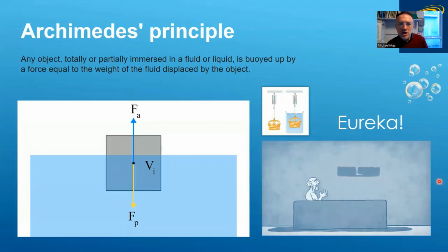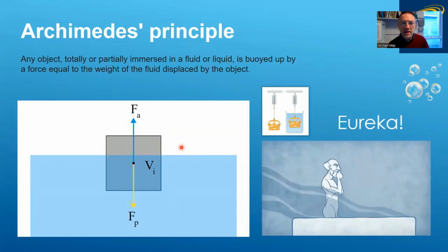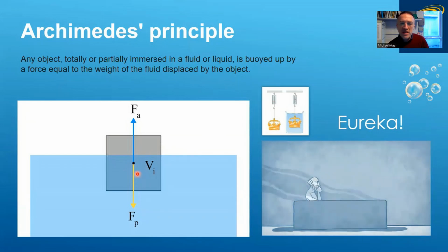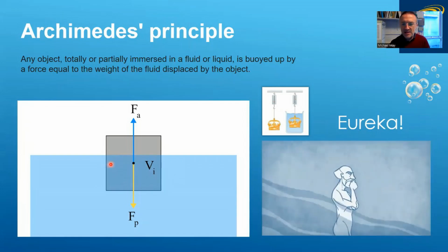So an extension of the Archimedes principle is that if you immerse a body wholly or partially in water, it is buoyed up or supported by a force equal to the weight of the displaced volume of water. And it's that principle that we use in our stability analysis.